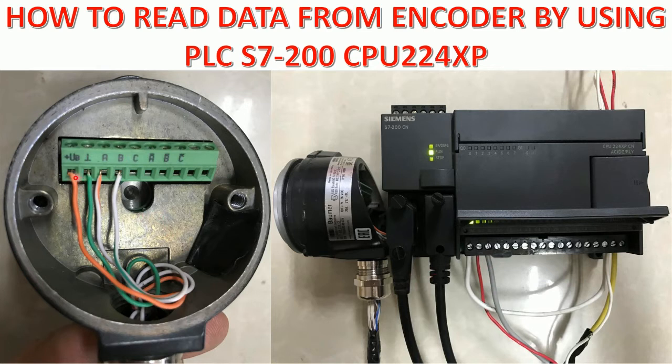Here is the voltage supply for plus, and this is the minus supply for the encoder, and these are the signals from the encoder for A and B, and we will connect them to this terminal.